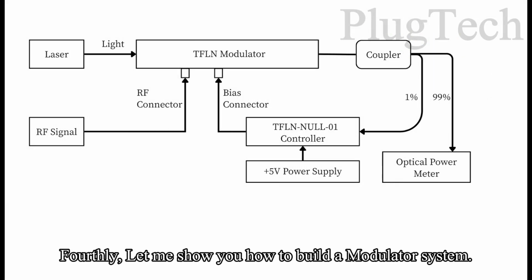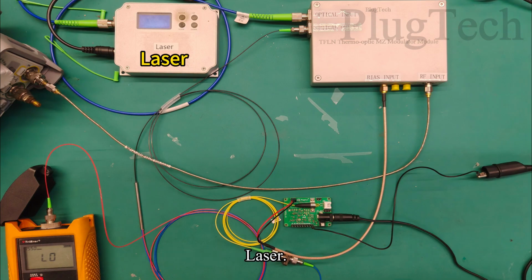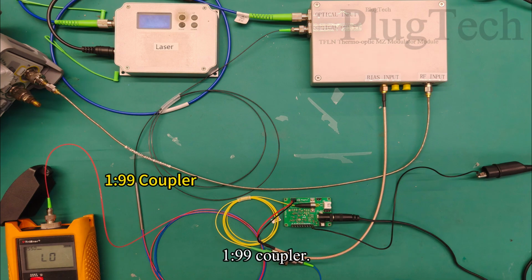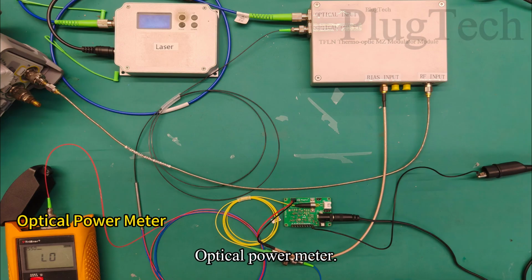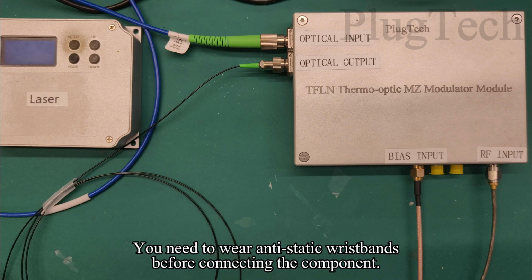Fourthly, let me show you how to build a modulator system. The system includes the following components: laser, Mach-Zehnder thermo-optical intensity modulator, 1:99 coupler, TFLN-NULL bias controller, signal generator, power adapter, optical power meter, ground wire. You need to wear anti-static wristbands before connecting the components.